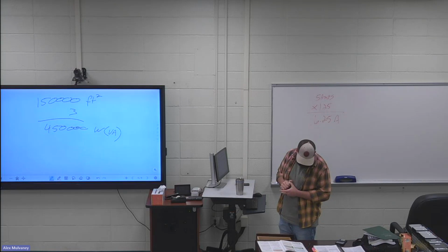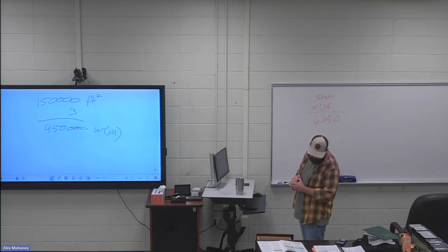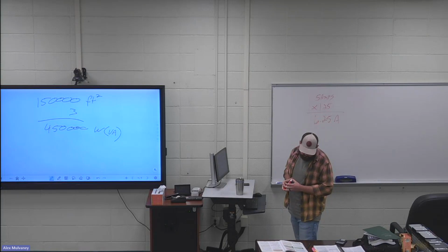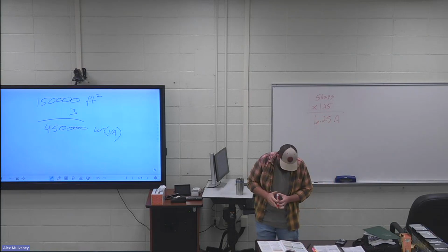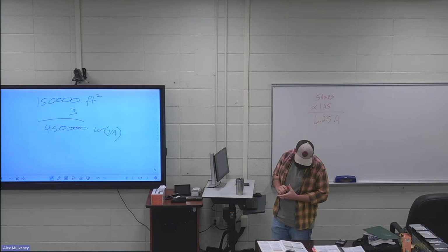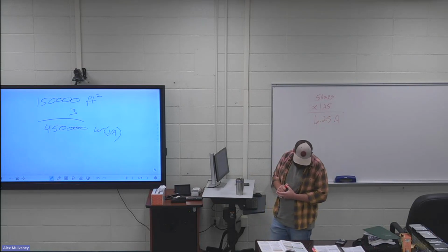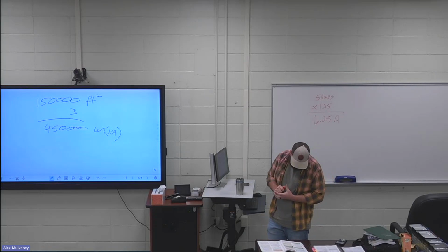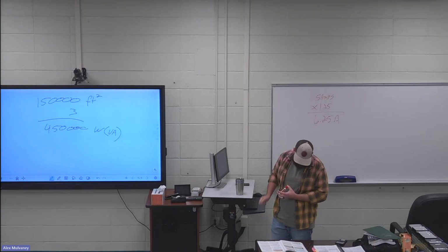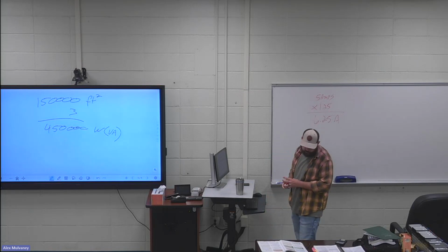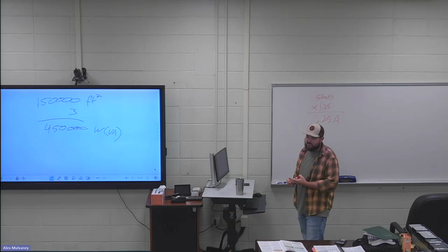Second to last paragraph on the page, right above example 1, the bottom right of page 2, that whole paragraph is highlighted. And this is an online test question: for 15 and 20 amp branch circuits, NEC 210.23(A)(2) allows fastened in place utilization equipment to be connected to the same circuit with lighting loads or lighting units, cord and plug utilization equipment not fastened in place, or both. Under this condition, the fastened in place utilization equipment cannot exceed 50% of the branch ampere rating.